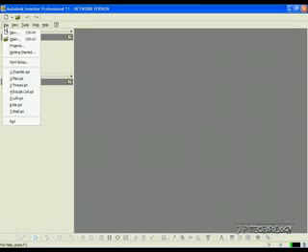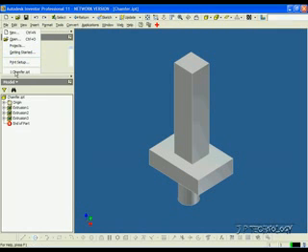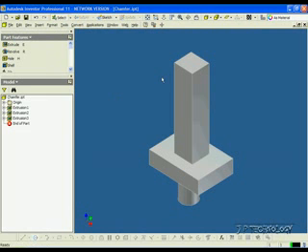This is tutorial number 20, and it covers the chamfer feature within Autodesk Inventor. Now to start off, let's open up the part. Let's click File, and click the chamfer part, which I've included in the DVD. Now what we're going to do on the chamfer is select an edge, and from that edge we're going to cut it off using the chamfer, so it's going to cut it off at an angle.